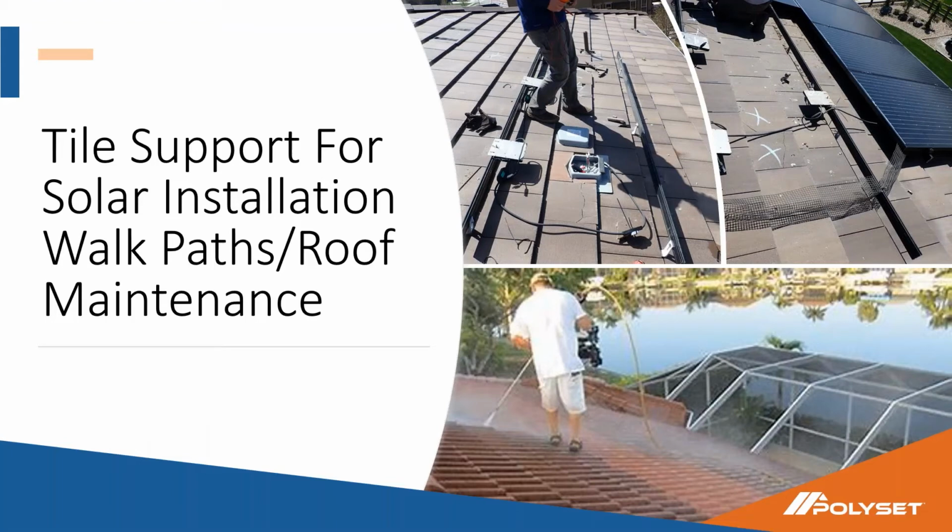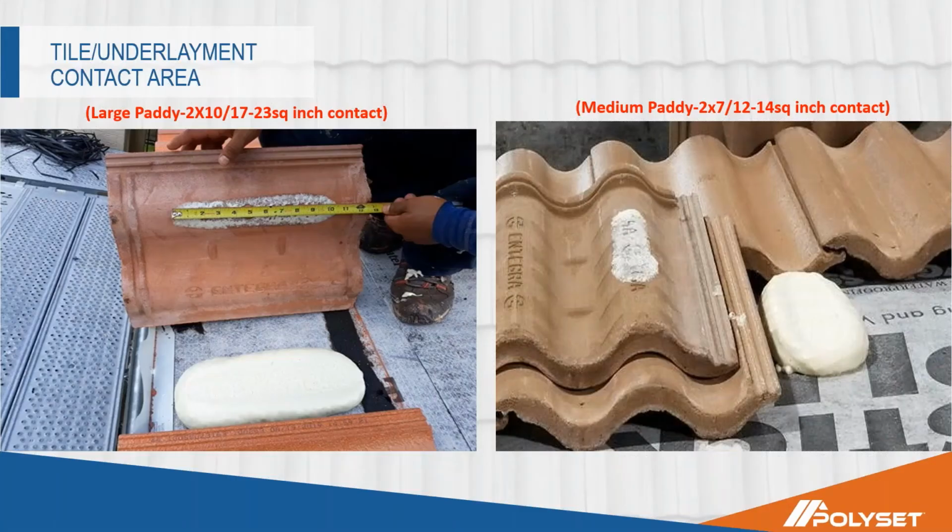We're getting a lot of calls now from contractors that are diversifying into offering solar systems as well. They're looking to put adhesive underneath the walk path areas of the solar mount system, and also some contractors that offer a pressure cleaning service to their clients. At 4,500 PSI, when you're pressure washing these tiles, they tend to create some movement, some tile lift, and some damage. So if you have a two-component tile system underneath each and every one of those tiles, they're less likely to have that damage associated with it.